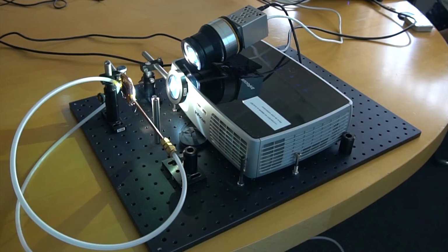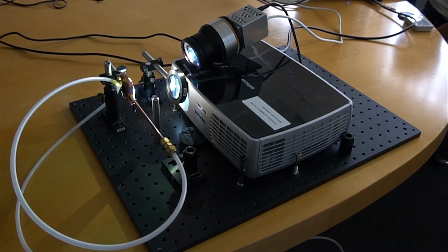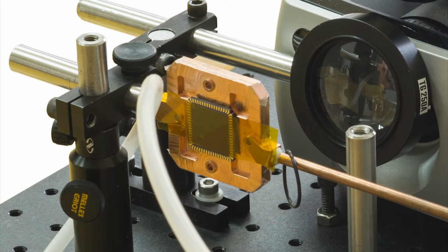The chip can only operate at reduced pressure, ideally in vacuum. It is quite understandable because the principle of conversion from the visible to the infrared is based on the absorption of radiation, increase of temperature, and then emission of radiation. Obviously, thermal isolation of each individual pixel, which will be heated with the visible radiation, is of great importance. For this purpose, the chip has to be operated in vacuum, which provides ideal conditions of isolation.